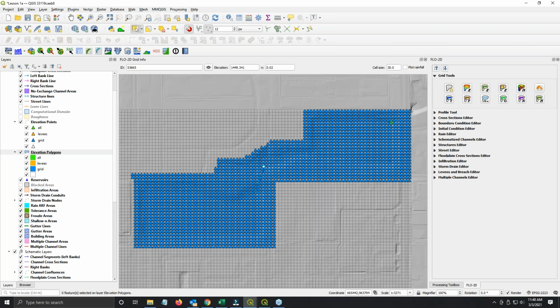So if you got your elevation data from your design team as points, that will sample the elevation from a TIN that was created by intersecting the points to the polygon, calculating a TIN, and then sampling that TIN from the grid.